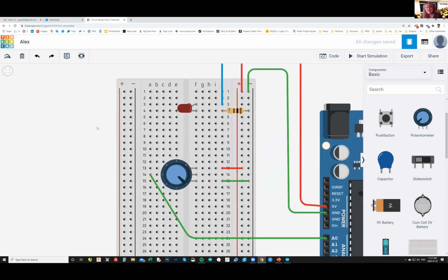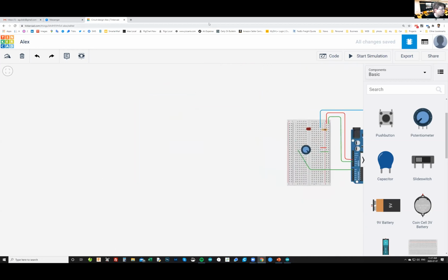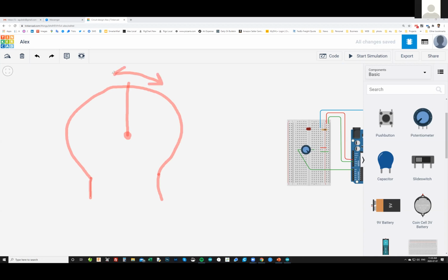So guys, if you break your potentiometer, I don't advise you to do it, but if you did, then what are you going to see? You're going to see one leg, another leg, then a little round track, and the center pin has a wire touching this little path. So when you spin your knob, this wire goes to the left or to the right.